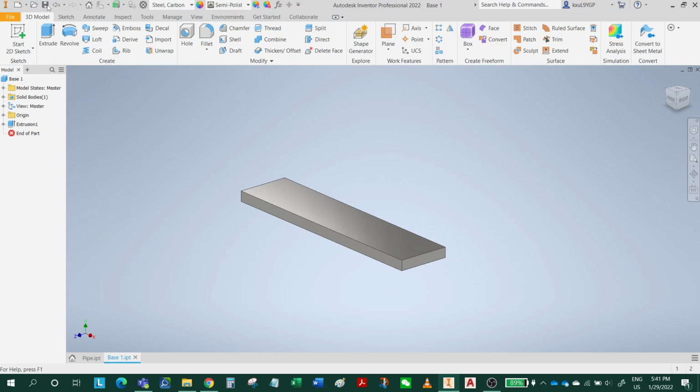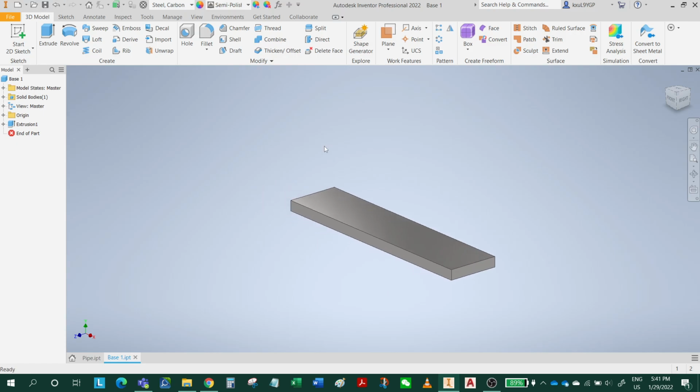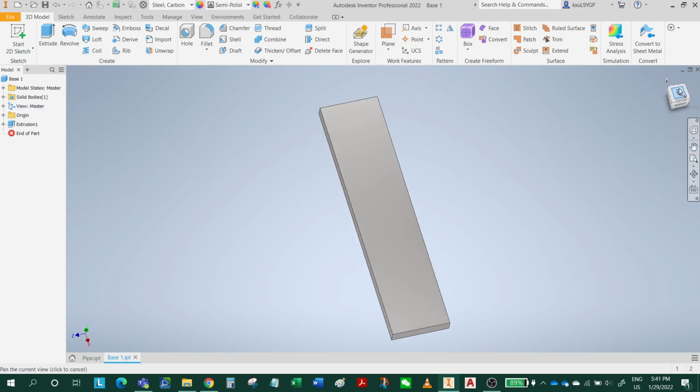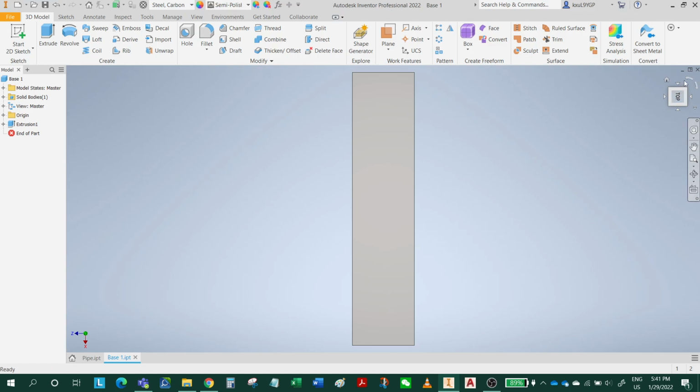So we save this. For the next part, we're going to create the large base plate. Actually, it's not finished yet. For this base plate, we have holes, right? If you go to the top view, you have two holes, which are finite, 62-degree countersink, 3 deep. You have two holes, one here.